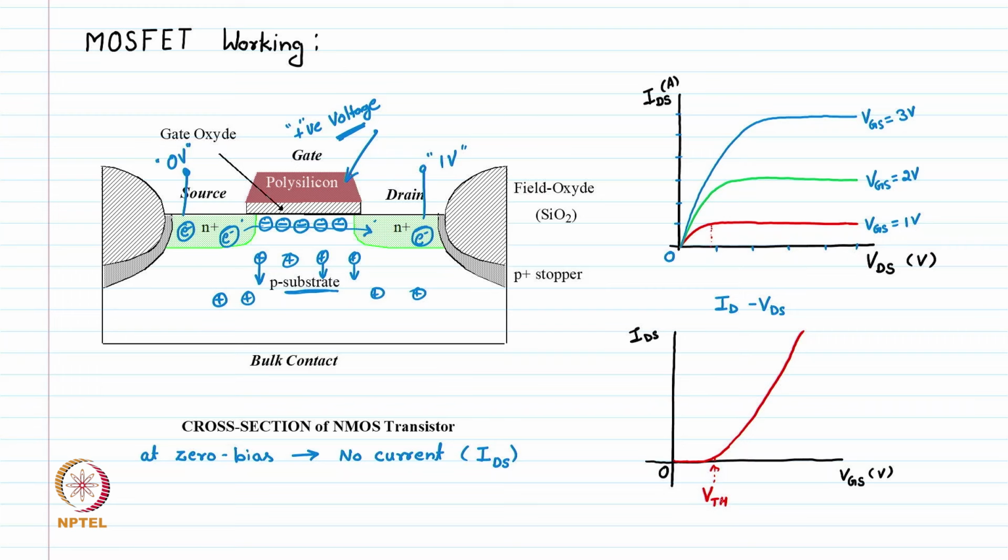So this is how this MOSFET actually works, and we have this threshold voltage which we can measure using the ID versus VGS graph, where the channel forms or the current sharply turns on. That point, the voltage which we apply at the gate, is called the threshold voltage.